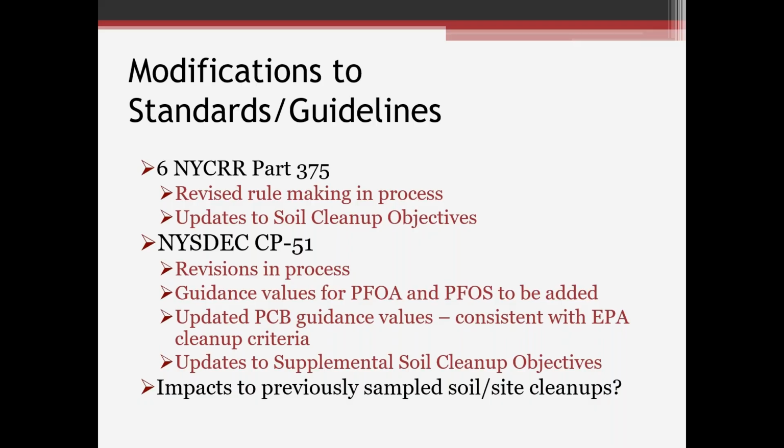For the most part, anything that was remediated under a previously existing standard is going to be good as is. But you do have to keep in mind that if there are property transactions and someone wants to investigate a site, whether it was previously remediated or not, you're going to be looking at those soil conditions against the current standard. So maybe it was remediated and determined to be below previously existing standards, but if you're doing that type of investigation, it might come up above those standards. Then you have to evaluate that. And again, that's a property transaction type scenario.